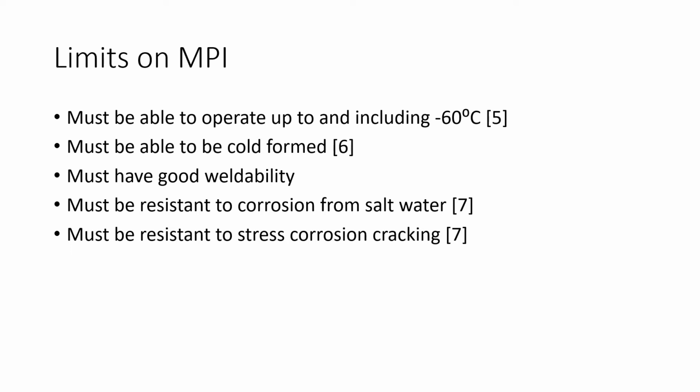Corrosion resistance from salt water specifically is necessary due to the road salt used to de-ice roads in Ontario, and thus will be present in the environment that the material will operate in. In CES EduPack, these factors have values like good and poor. As such, we chose the good and excellent values to ensure a suitable material.